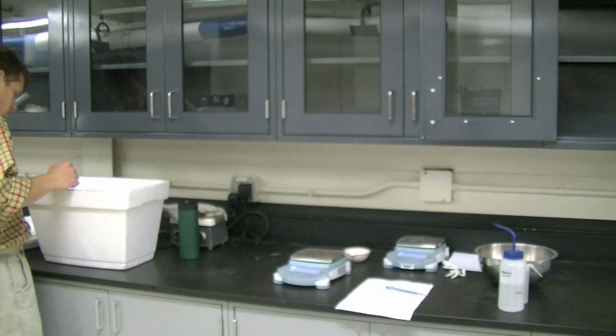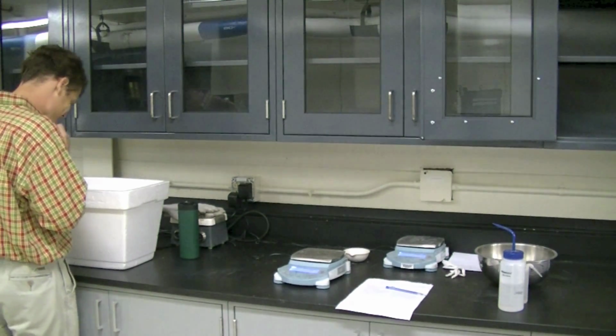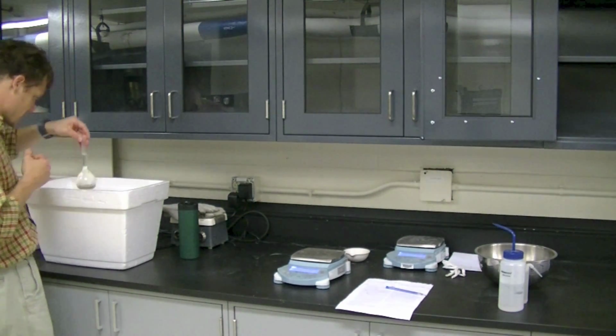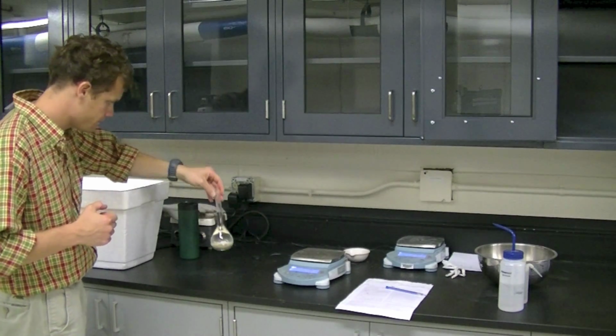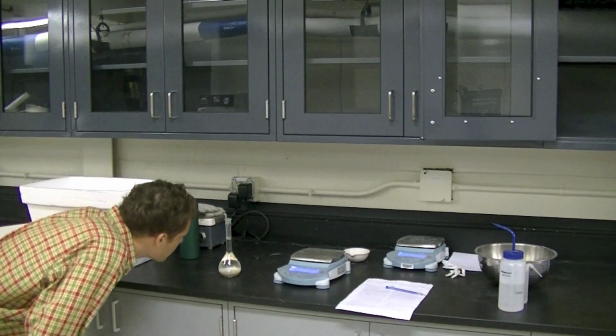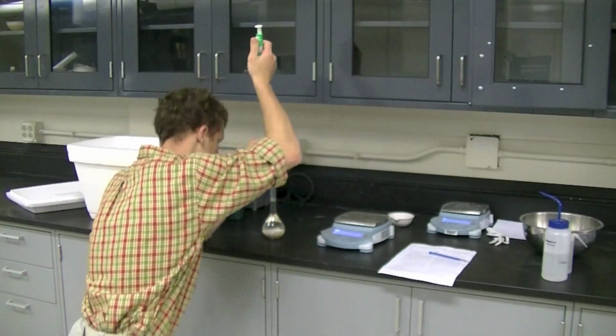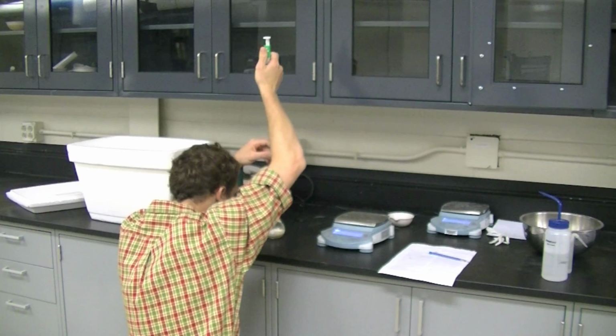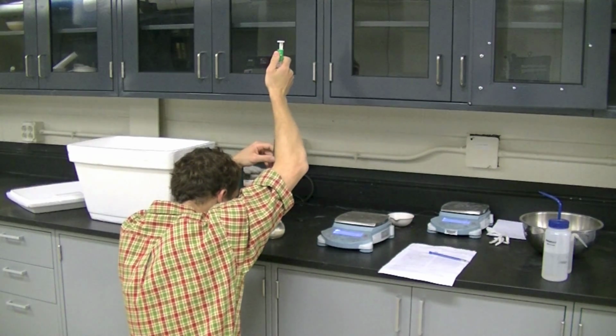Move the insulated container near the scale if it is not already there. Open the container and remove the pycnometer, handling only the rim to maintain equilibrium. Adjust the water level up to the calibration mark, using the same tip insertion method as described. Use the deaired water from the container.